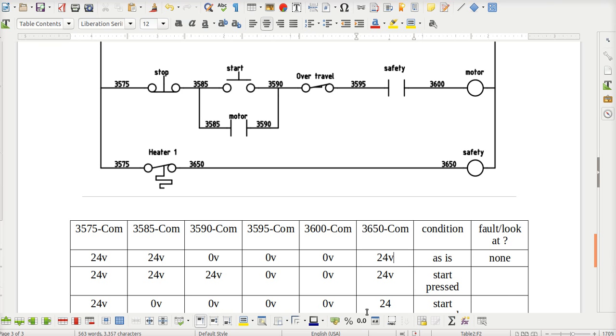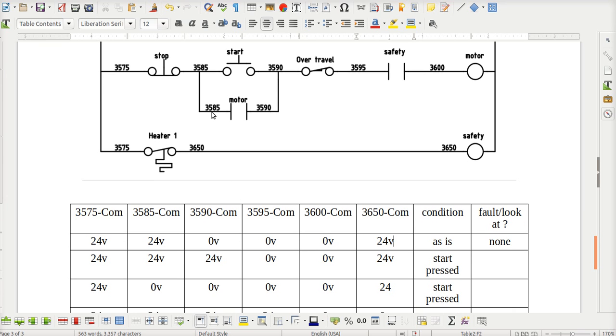And so then I've got different fault levels in here that you can troubleshoot, and you can basically go in and you can open and short everything. I could short this set of contacts. I can open this. I can open the stop button, which I think is one of these. I can open the heater and just figure out why the circuit doesn't work.